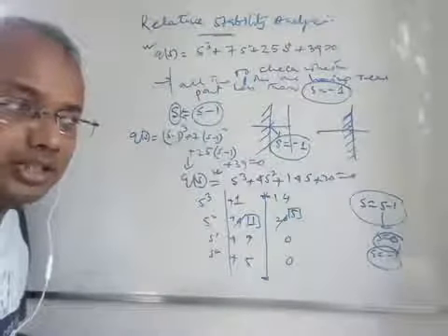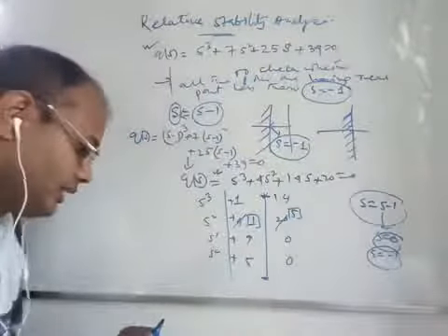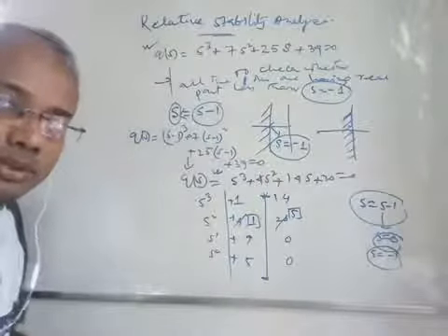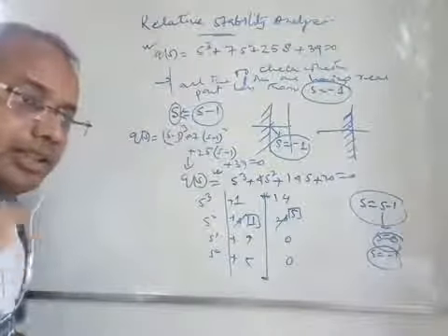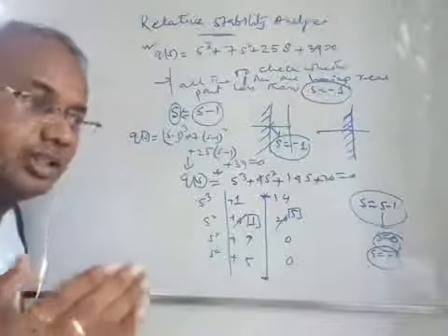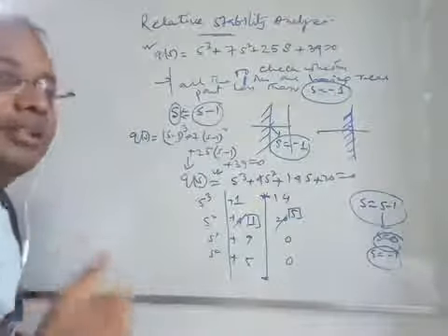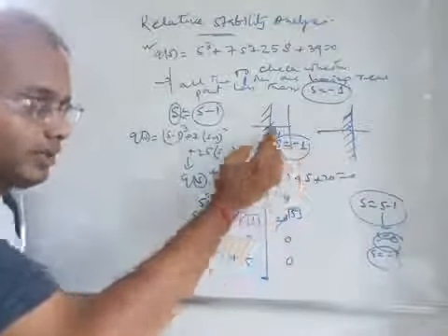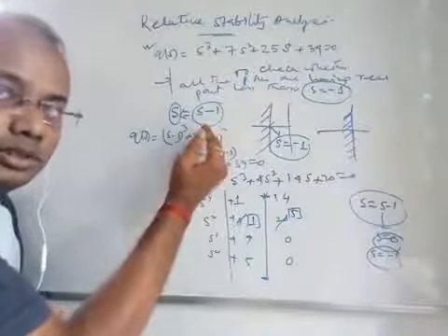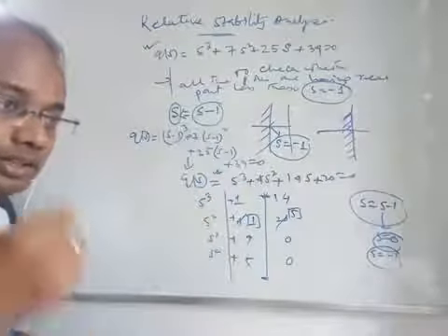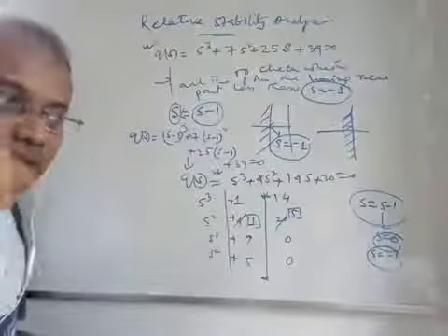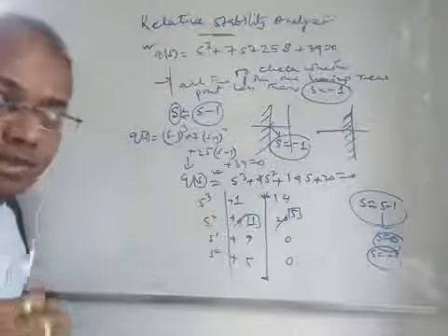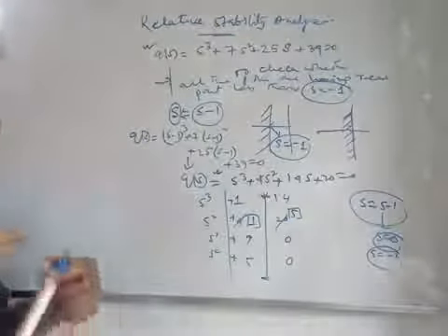So once the system will be unstable, you just leave it. That means the real parts of the poles of that system cannot be taken to the left hand side of this. That means up to that level the system can be made stable. That means settling time may be made faster. The system stability remains the same. Here also the system is stable, here also the system is stable. Maybe to the left hand side of that position also you will get the system stable, but the settling time is actually decreasing. For the same system, stability can be improved to some extent, right? So that is the concept of relative stability.